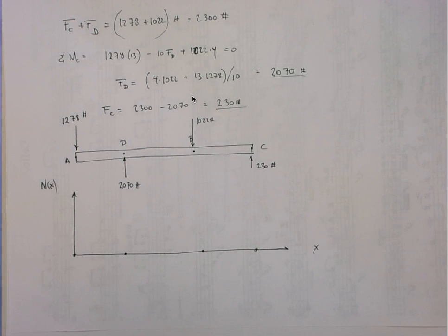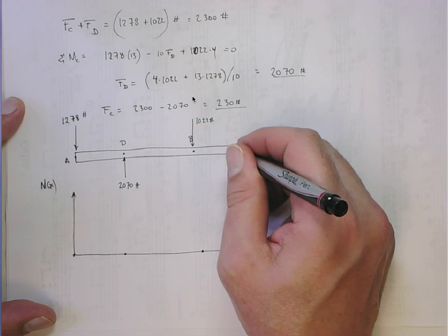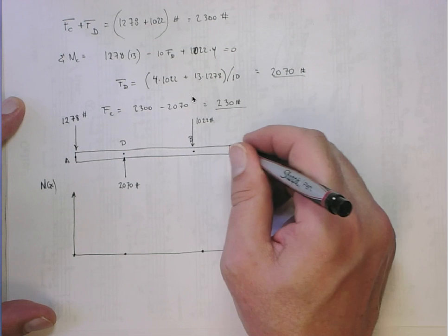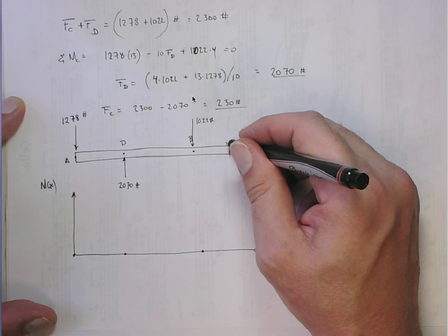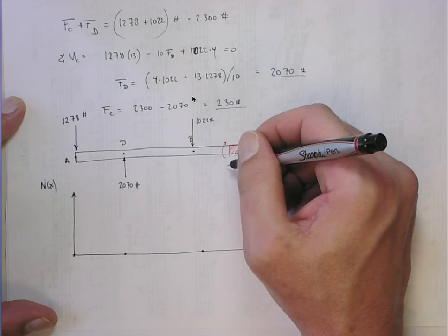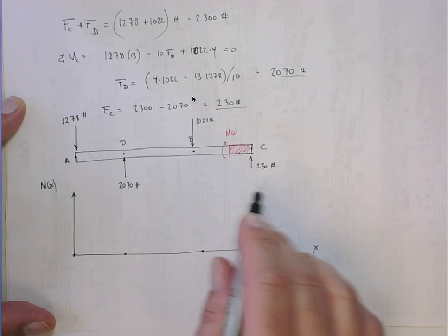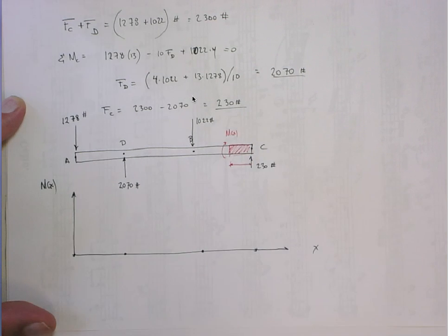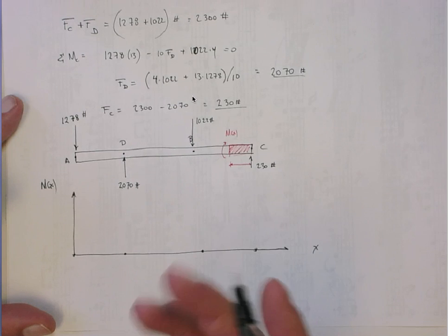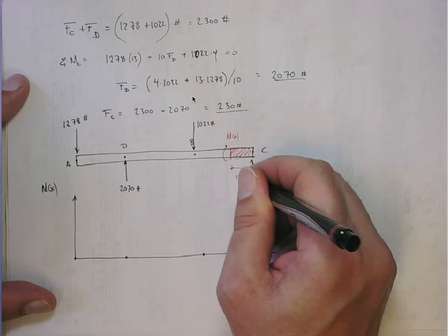Now, if you think about it, let's start going from the left-hand side. So if we draw a section through here, right? We draw this cross-section. Then it'll have a bending moment, the internal bending moment acts clockwise because it's a negative face. And so this distance here is the total length, which is, what is the total length? 13 minus x, right?